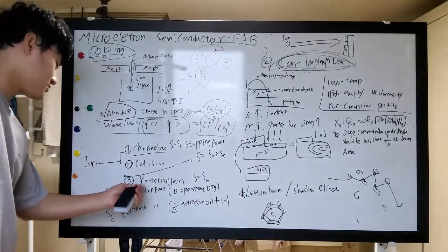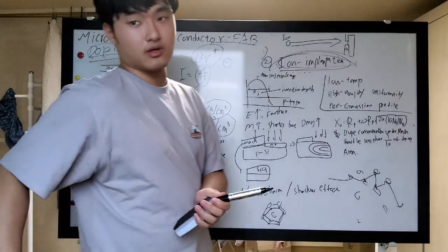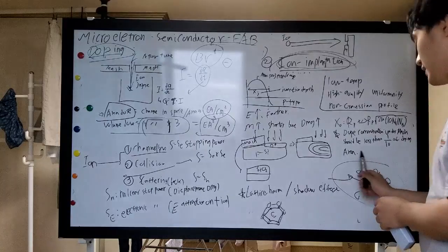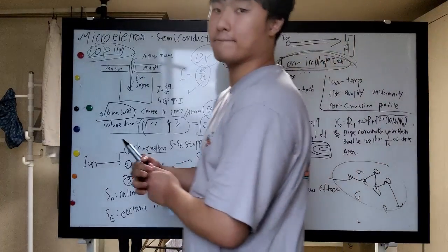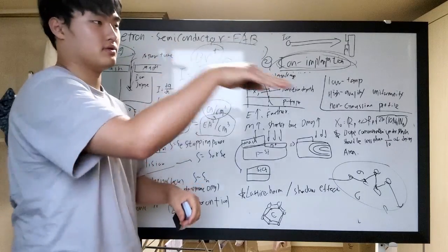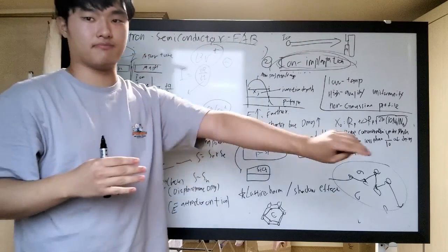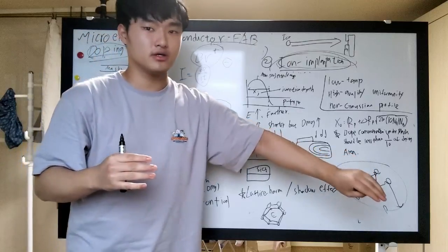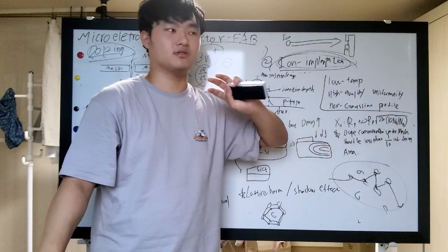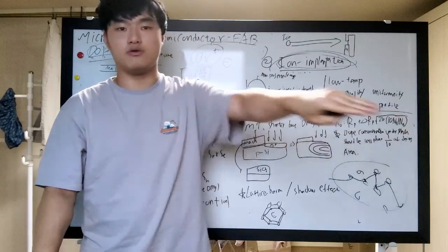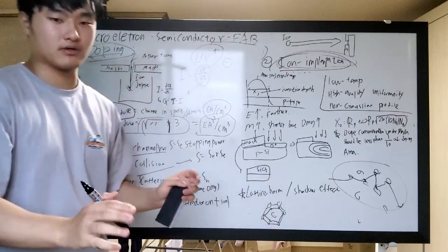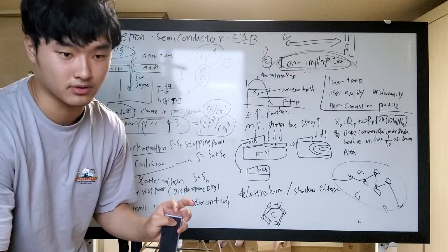And finally, the scattering, especially the back scattering. It is similar to the topic I just talked about with collisions. But back scattering means repeated collisions, impact and reflect, impact and reflect, and finally, with a moderate angle and some inner energy, the ion is reflected backward to the injected side. So the doping will not go as we wanted.